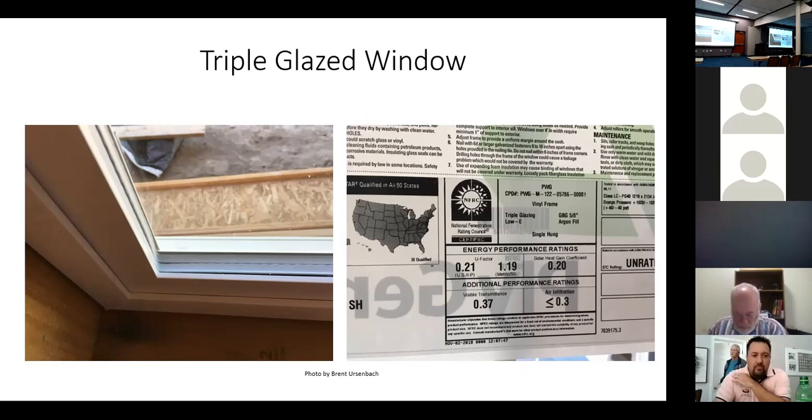Is the thermal, the commercial windows, they have like a glass that I guess has a lower solar heat gain coefficient, or is this as good as it gets? No, well, I mentioned dynamic glass. Dynamic glass is actually glass that, by putting an electrical charge on a film on the glass, you can darken it.